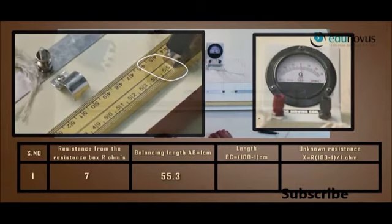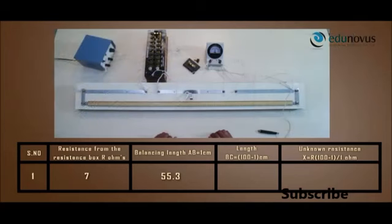Therefore, length BC is equal to 100 minus L centimeters, which is 100 minus 55.3 centimeters. Therefore, balancing length BC is equal to 44.7 centimeters. Unknown resistance X is equal to 7 into 44.7 divided by 55.3, which is 5.64 ohms.